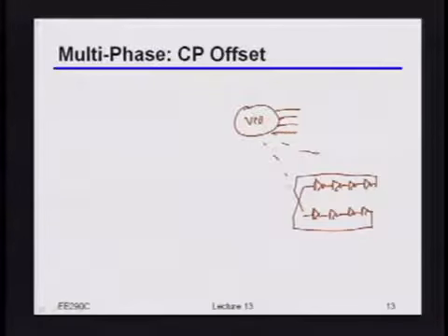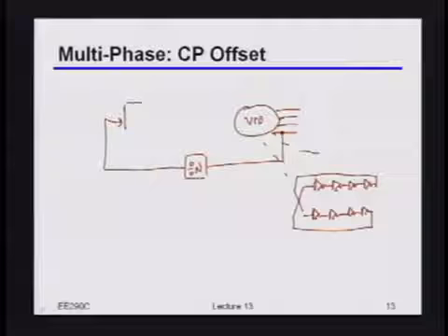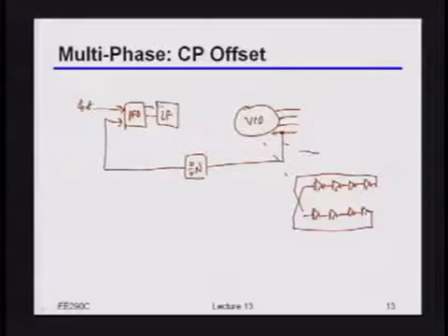So if I can just shift whichever phase it is that I use to take the feedback off of. Right, so let's say that's my PFD. That's my reference clock. And I'll just draw my loop filter here. Actually, I'll really draw it this time. So now I'll actually draw the charge pump just because you'll see in 1 second I'm going to be mucking around with that a little bit. Okay, so that's my charge pump, of course, my loop filter.